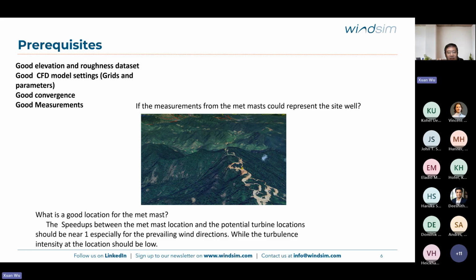For example, you set the convergence criteria to be 0.0005, and when the iteration of the CFD simulation ends, how close the residual has reached, or what's the difference between the residual and the convergence criteria. You could actually use accelerator to check that. Maybe later I could show you guys.